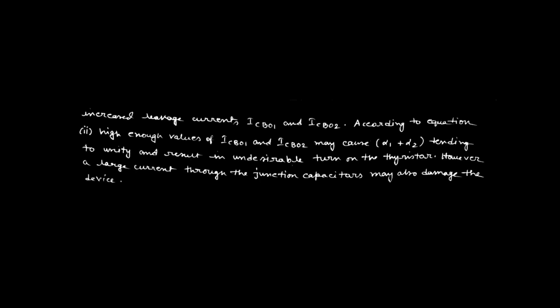That means we can conclude that if we inject a small amount of gate current, then the device will be in conducting state. The whole thing is represented by the two transistor model, which well defines the turn-on process of the thyristor by using the two transistor model. Okay, thank you.